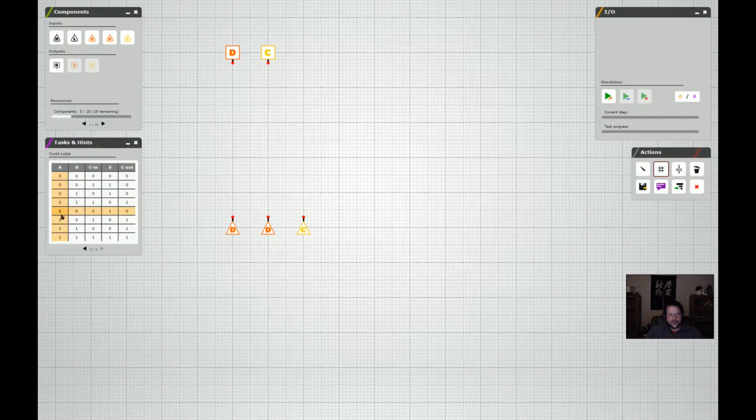So the middle ones here, though, they're mixed. We've got A being 1 here in these two, and B being 1 here in these two. If we look at the results of these, in this case A is 1, B is 1, and sum is 1. But in this case, we're bringing in the carry in, and sum is 0.